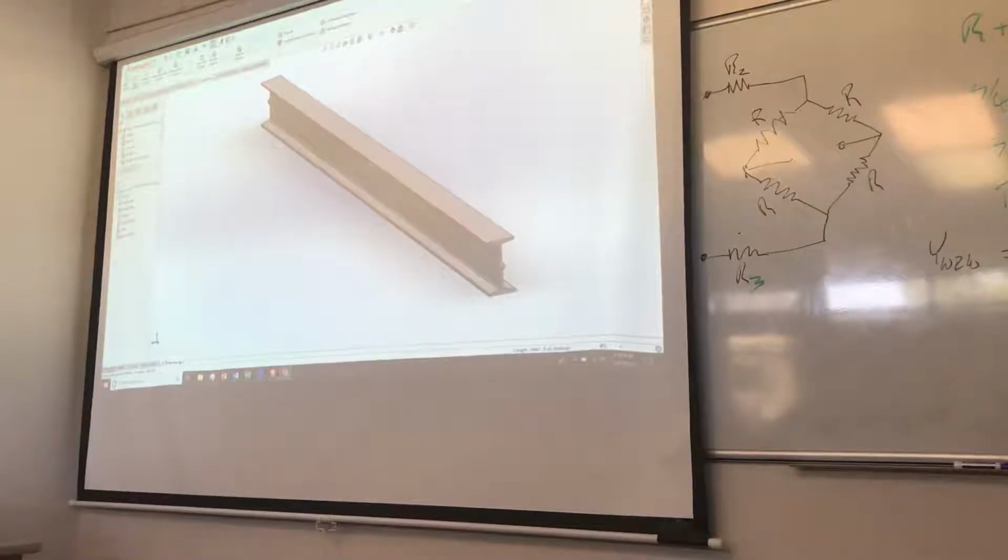So anyway, we have these. These are indications of what it calls joints. When SolidWorks makes a model out of beams, it puts joints at the ends of it. There are places where other things can join to. Okay, and so it indicates where the joints are in your beam model with these balls. This is a place where we can apply constraints to. We can apply loads to them, we can apply displacement constraints, other things.